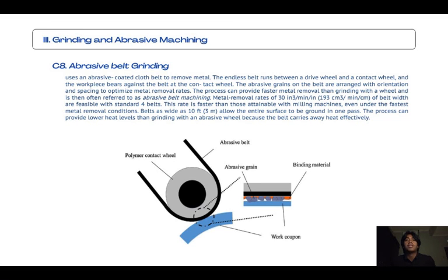in ceramics, glass, carbide, tool steels, honeycomb materials, and gemstones. Holes and cavities can be non-round and curved. Material removal rates are low, but there are no heat effects, no burrs, and no surface stress. Holes do have something inherent, sidewall taper.